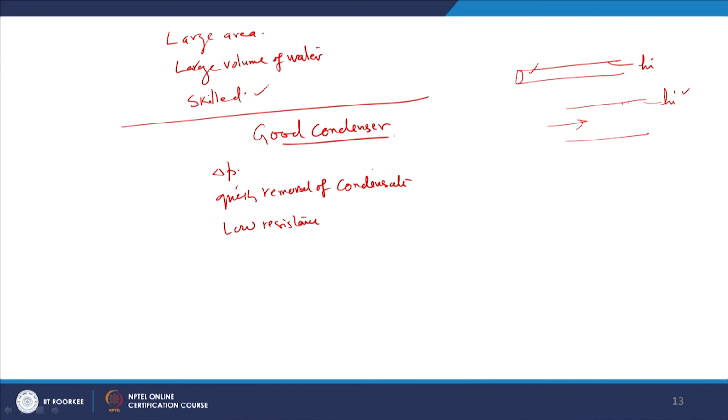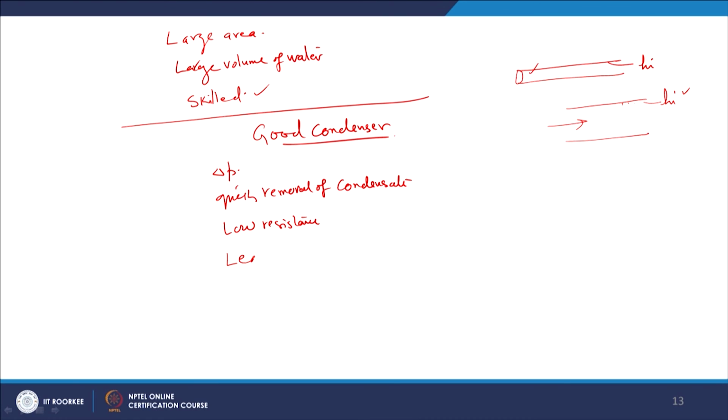In this case, surface condensers, because they are often not insulated, the heat loss through the condenser wall by convection or radiation should be minimum. Leakage of air is a main issue. So, air leakage has to be minimized in a surface condenser. But the possibility cannot be made absolute zero, because air will anyhow enter the condenser because it is running at a very high vacuum.